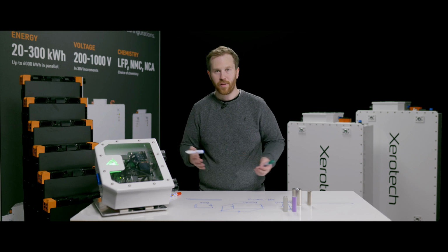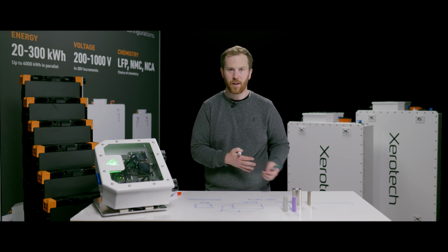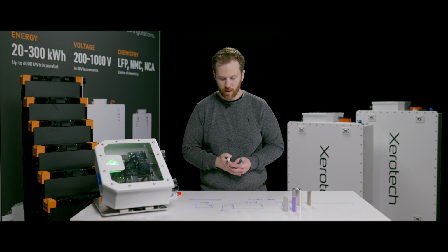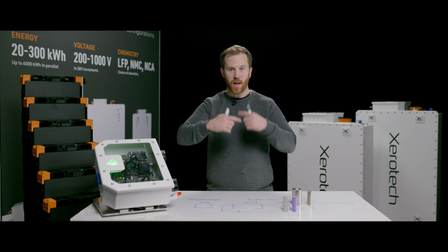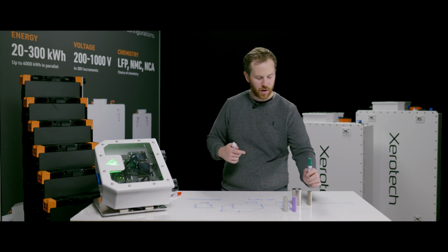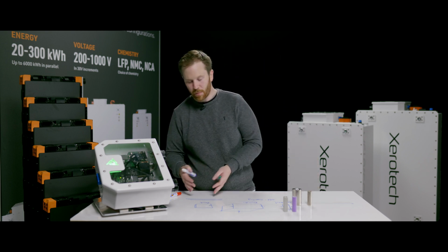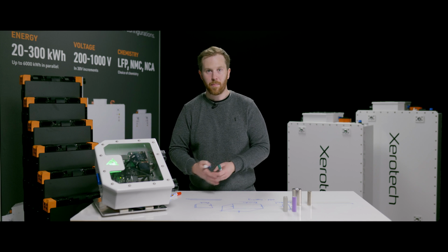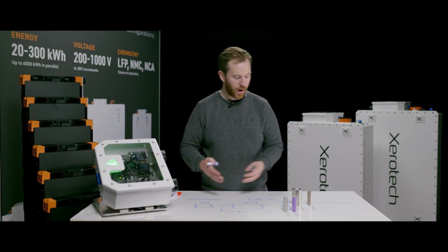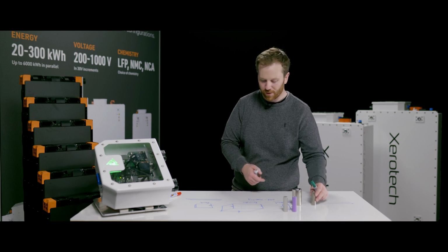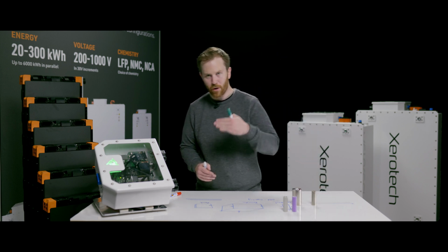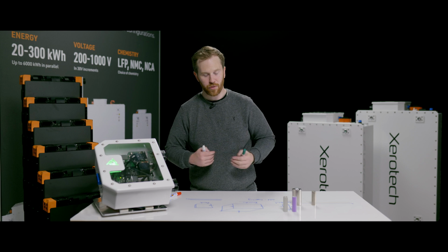But if you've heard of solid state batteries that have solid electrolytes or different types of separators, that material is not flexible. And what that means is you can't wind it up. You can't actually put it into a cylindrical cell. So some advanced chemistries are available in pouch format only. Now there are other types of solid state batteries that can be wound up and put into cylindrical cells, or prismatics that are done in a sheet format and not a compressed jelly roll.